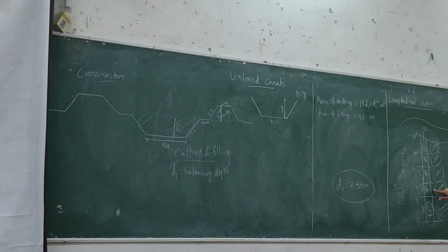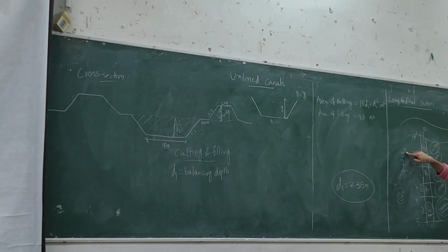So just going back to the longitudinal section. Designing the section between 4 to 5 kilometers. If the discharge required based on the crop requirements is, let's say, Q4. Now for this Q4 there is 10% loss or there is 90% efficiency. So we are considering Q4 by 0.9, and we also should consider the losses that happen between 4 to 5, so that would be 0.1 times Q5. So when we design the section between 3 to 4, this is the total discharge that we need to consider.